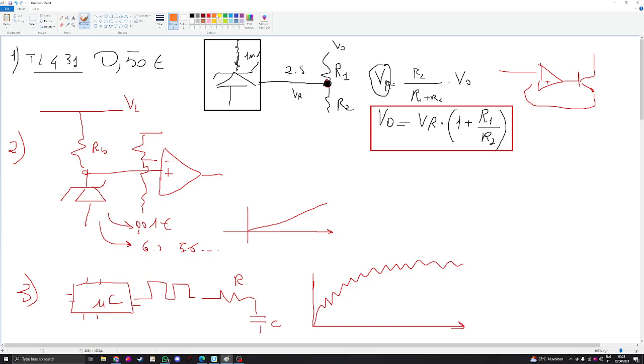Now, two important points. First, you notice that there is a DC component. This DC component is directly proportional to the duty cycle D of your PWM. The higher the duty cycle, the higher the DC component. Well, you can imagine that.